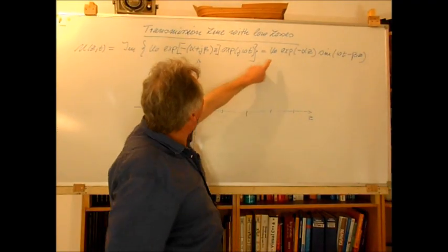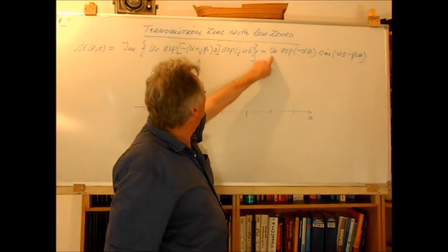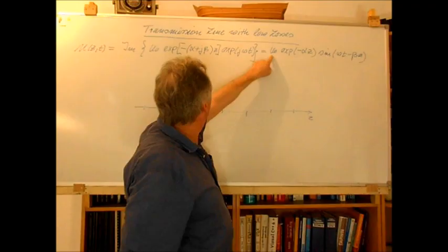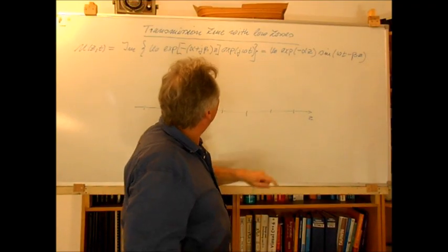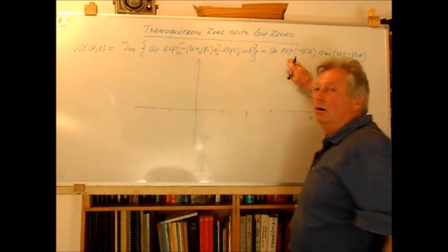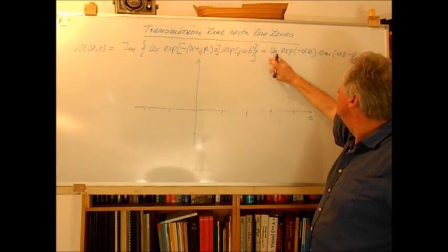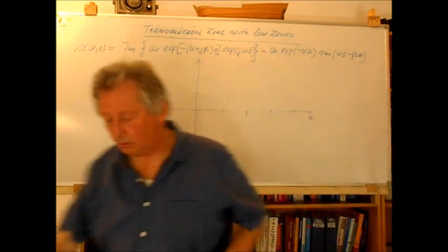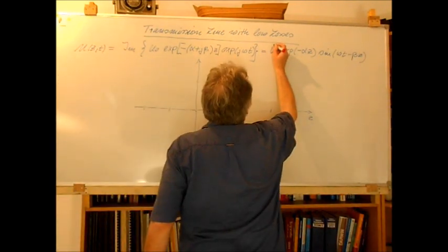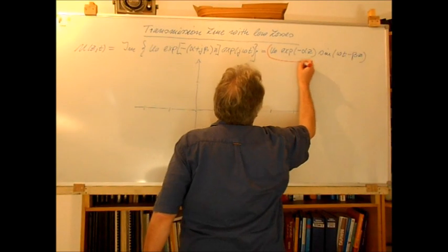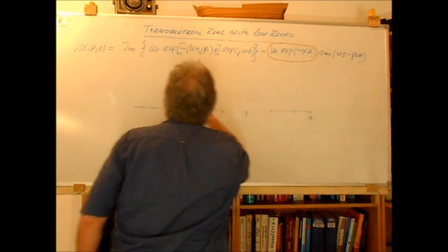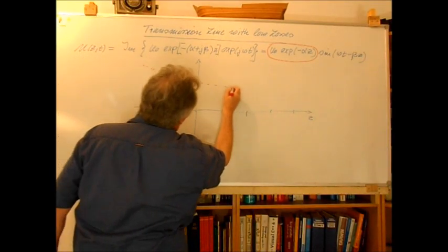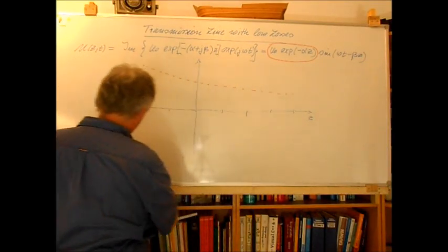the voltage will be the same. Of course this will describe in principle the voltage of our transmission line wave, but according to this function the voltage of the transmission wave will decay in the x direction. So I will draw this. Now this term will result in a decay of the amplitude. This means we have an exponential decay of an amplitude which looks almost like this.